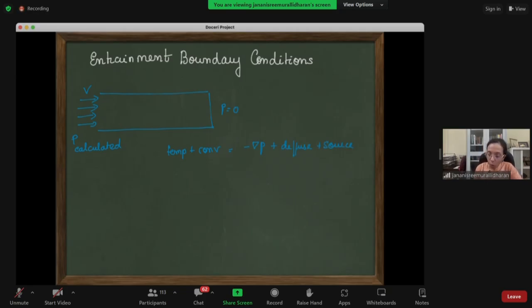So when you specify a velocity at the inlet, there is the mesh. You're going to calculate by solving each mesh and going forward, correct? So there is a clear velocity boundary condition at your inlet which will set up the flow. You know the velocity there. So when you know the velocity there and the back pressure at the outlet is known, the delta P gradient, because you'll be solving by the SIMPLE algorithm, there's a pressure equation, correct?